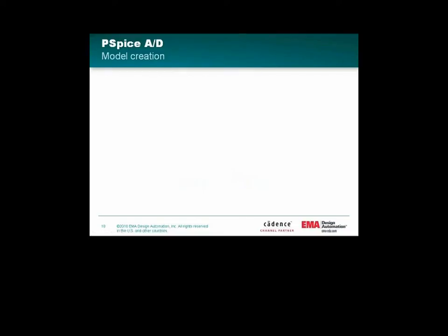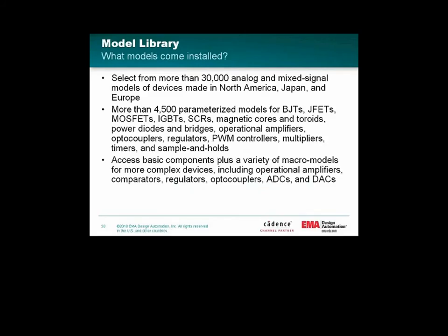Okay, so that's it for the tips and tricks section. What I'm going to do is move on to model creation now. In model creation, I'm just going to talk to you about how you can bring a model from the web into your tool. There are other things that you can do with the model editor, and I'll mention some of them, but I'm going to focus primarily on grabbing a model from the web and bringing it into PSpice to use it.